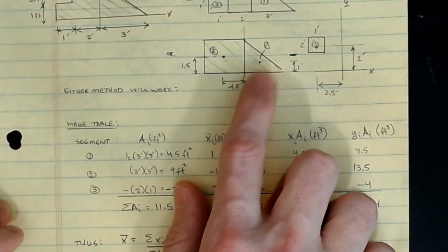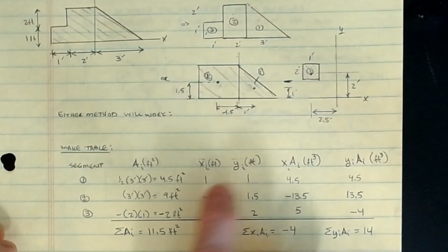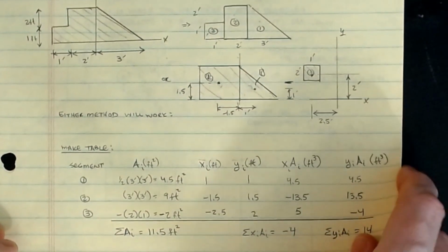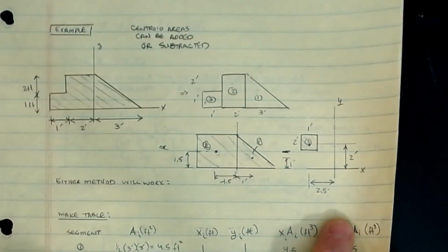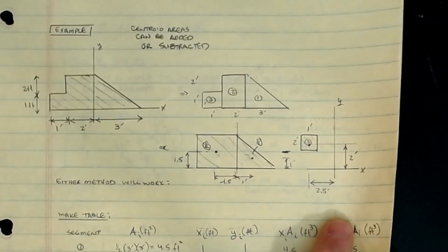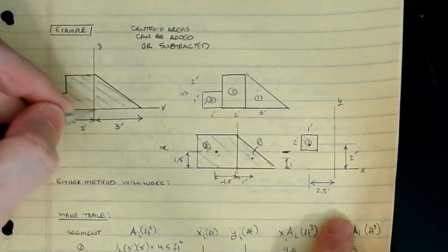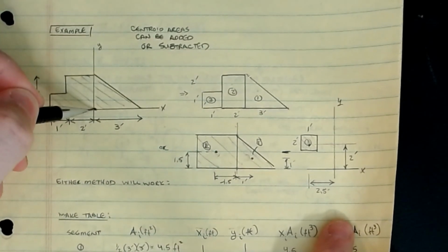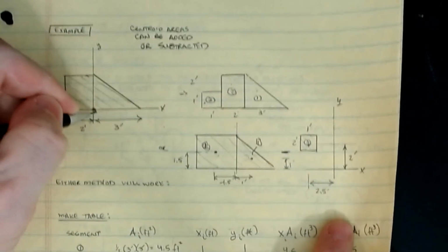Okay, the centroid of this, now this depends on these xi, yi dimensions, which are measured relative to a reference. In our example, you can choose the reference to be anywhere that you want. Again, in my class and problems, generally you're given that, or you will assume that it's the lower left or something. But for this, they're assuming that the reference is here. You can see you've got your x-axis and your y-axis, and this is the origin. This is the reference point. All right.